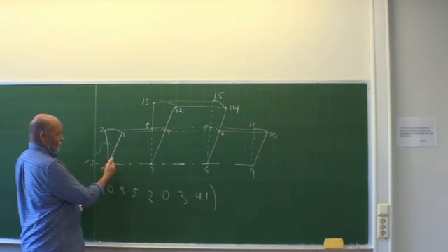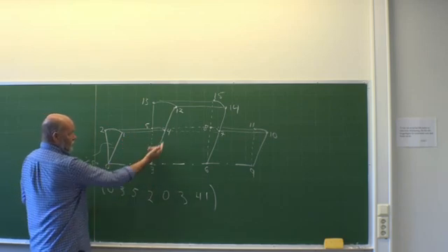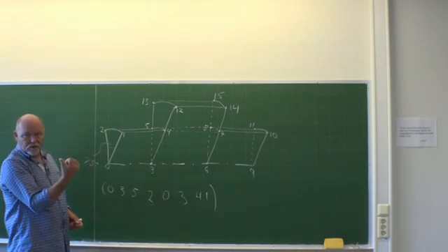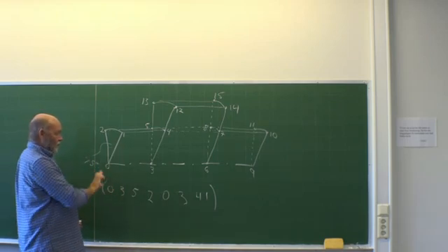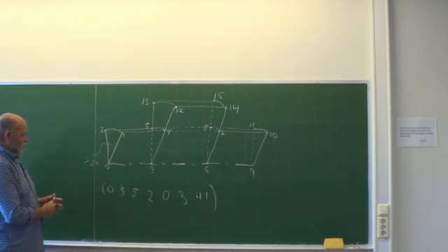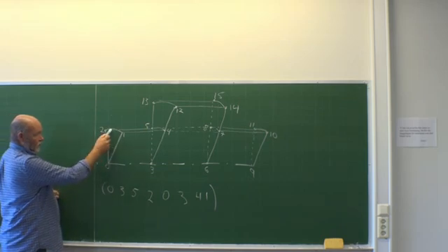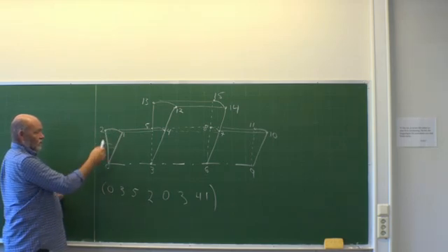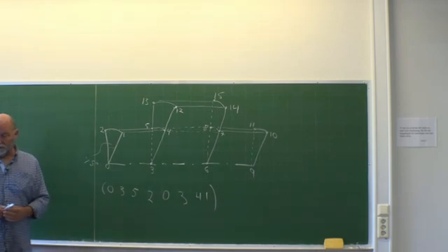So say the face for the front here, it will be 0, 3, 4, 1. Then you have a normal vector on that face pointing out. On the back face, you should then go the other way, 0, 2, 5, 3, and it will point the other way. And now this face here, well, it is a little strange, isn't it? It will be 0, 1, 2, and then back to 0 again. So you will have 0 twice. Why not? So that is sort of how we operate such meshes.